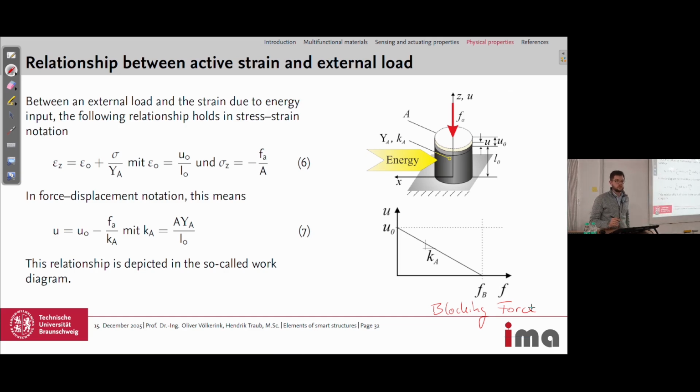So electric field, will it be active during the pushing back? Yeah. Otherwise, if you remove the electric field, then the transducer will shorten again. So the elongation is just due to the active electric field. So you have the active electric field and then push it back to L0.